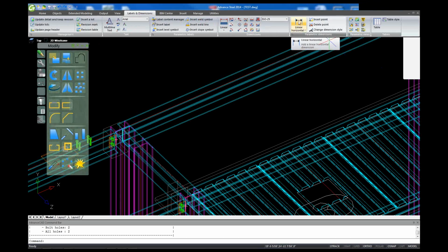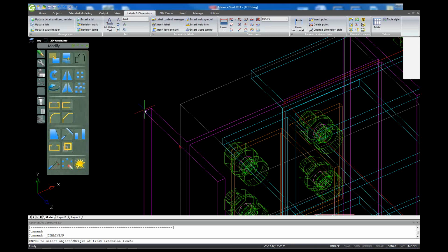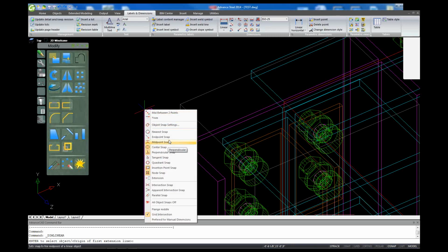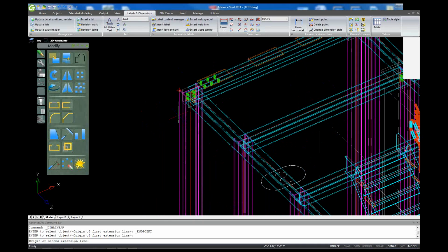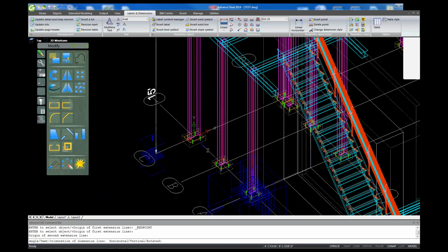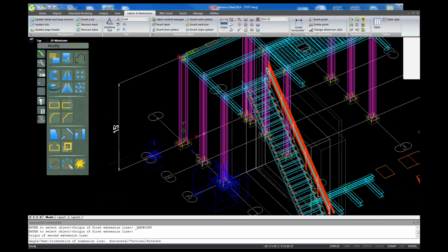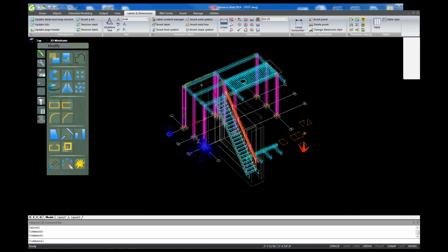By the way, James, you are not using this. This is for 2D drawings. So a quick way to measure, we can just go there, right? I like using endpoints. So yeah, see, it's 15 feet. So that 15 foot you saw a while ago, that is the elevation. Always within the Z-axis, it's the elevation.